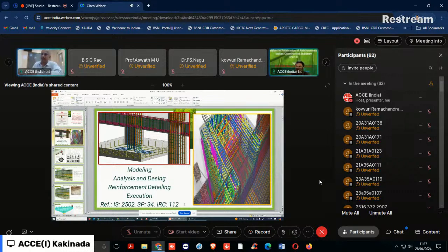And also the L bend requirement, generally we make some sort of mistake. Generally, the L bend is put on all the sides. That is not generally required. That is a wastage of steel. Why? Because the L bend requirement is a function of the development requirement beyond the face of the column. That is the critical section for the flexural bending moment. Suppose this is a cantilever bending moment at the footing edge, with a critical section like this, in the form of a vertical plane, and beyond that there is the fixed zone for the anchorage of the steel. Take this bar into consideration.